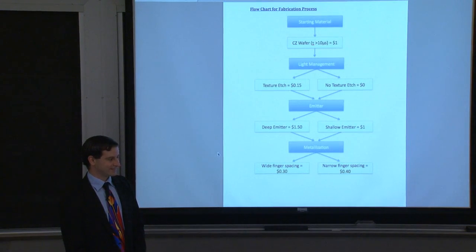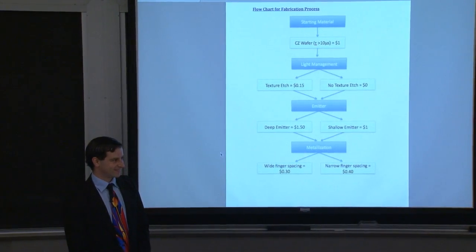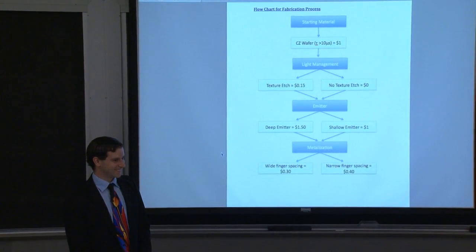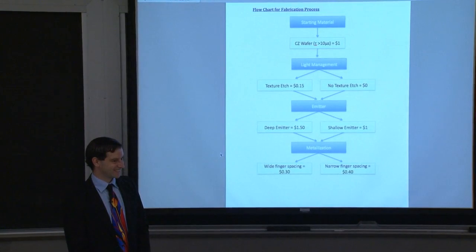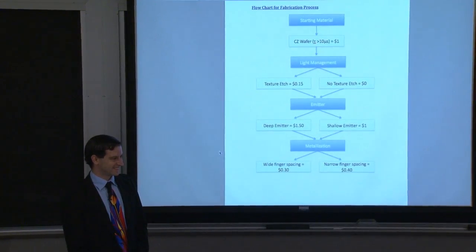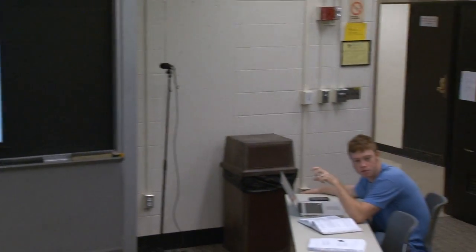I mean, so in terms of shunting your device, it's really hard to predict the shunt resistance, but if you do shunt your device, you essentially ruin it. So I would just take that into account. I mean, this is meant to be, yeah, you're not going to get exact answers. But you can do your best to estimate series resistance from the finger spacing and your emitter thickness.